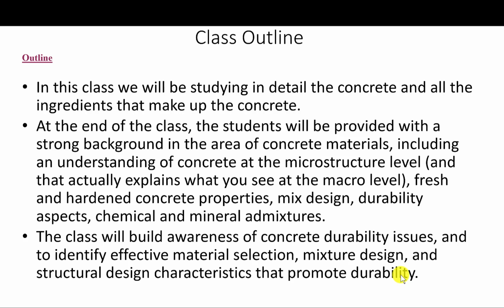Fresh and hardened concrete properties, mix design, durability aspects, and chemical and mineral admixtures. This class will also build awareness of concrete durability issues and identify effective material selection, mixture design, and the structural design characteristics that promote durability.